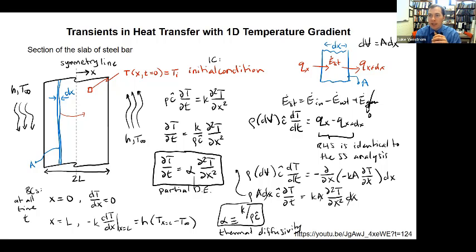And it's a parameter that's going to essentially tell you how quickly the energy is going to get in or get out. So the higher the thermal diffusivity, the faster the temperatures are going to smooth out and come to a new equilibrium, right? It's a balance of both the conductivity, which is how fast it's happening, and the storage of the material, which is the specific heat. So how much energy do I have to move to get the temperature to change? And the higher the diffusivity is, the more rapidly the temperatures are going to change in any location, either because there's a low capacity or there's a high thermal conductivity, or both.